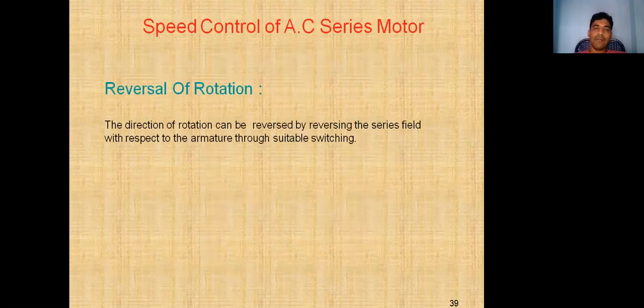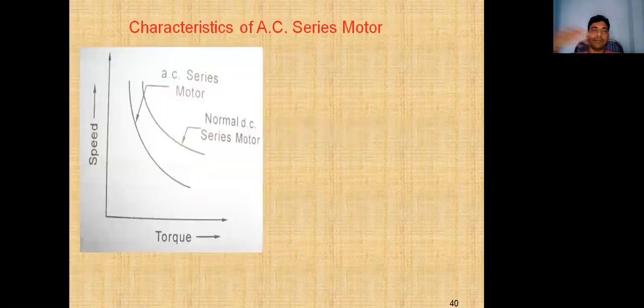Coming to the reversal of rotation. The direction of rotation can be reversed by reversing the series field with respect to the armature through suitable switching.